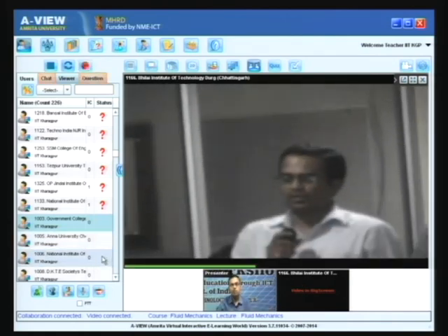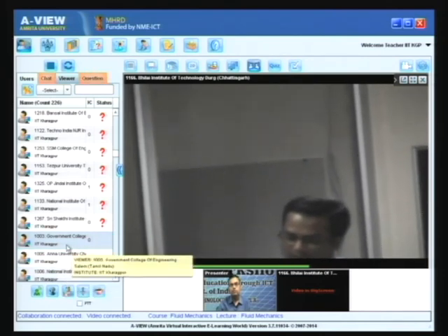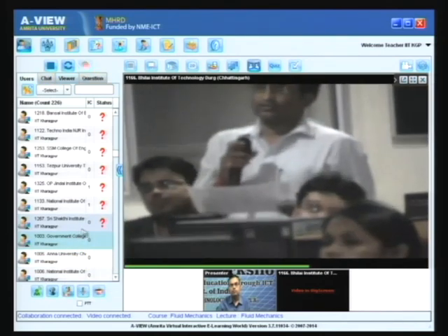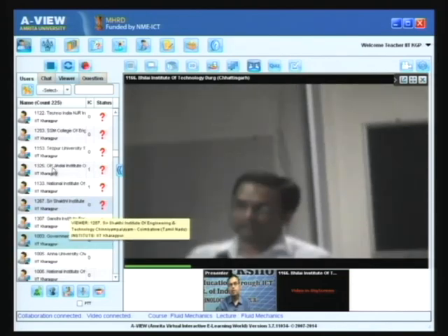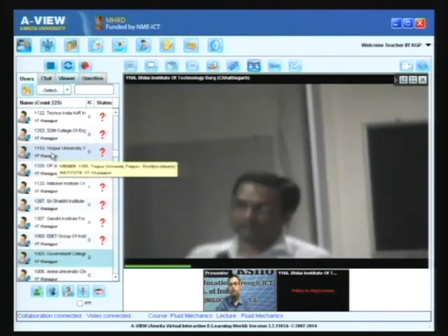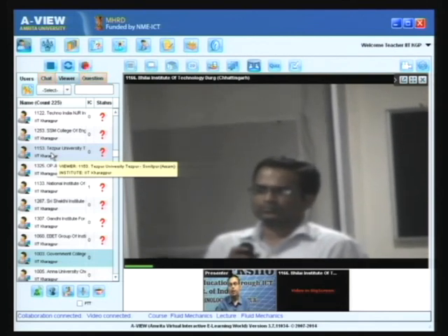Hello sir, to get the capillary height I have to get the value of theta as well. How will I get the value of theta? There is a particular way in which you can measure contact angle. You can form a droplet on a substrate and take an image of the droplet through a camera.